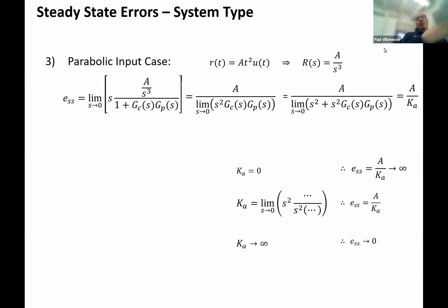If you're trying to track something moving in the sky, like if you're part of air defense, that might be a ramp input, right? Because you're tracking its position, it's rotating, so its position is changing relative to time. So that's not a fixed input. That's the length of something increasing. So that would be a case where perhaps you have a ramp input.